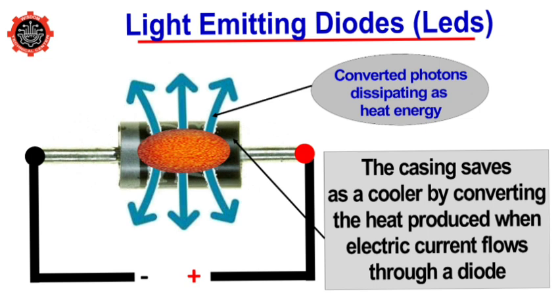The cable small. So whenever you use any cable or you see any cable wey dey warm, know say that cable no correct for that particular use wey the cable dey work for that moment. If the cable dey hot, means e no correct. You get for change and use big cable.